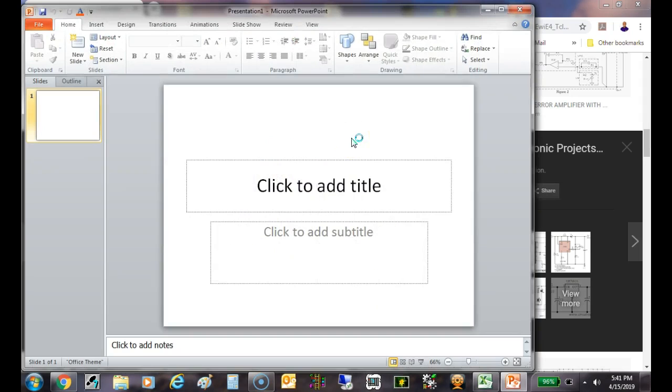So conductors are not rated in voltage. What are they rated in? We only got three things, guys. We got voltage, current, and resistance. What are conductors rated in? That's not what they're rated at. It's called ampacity. How much current can that chunk of wire handle, right?